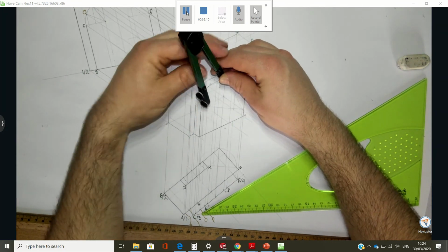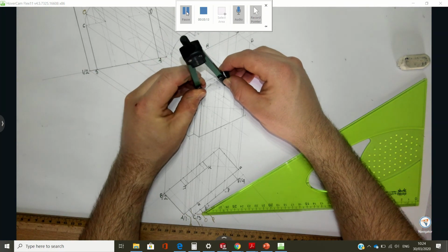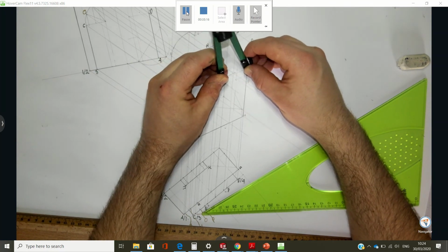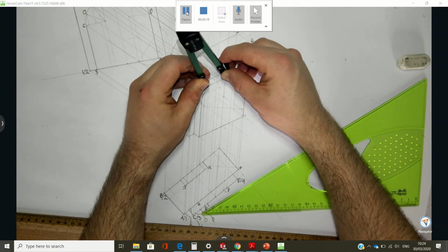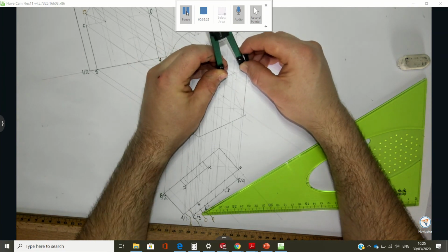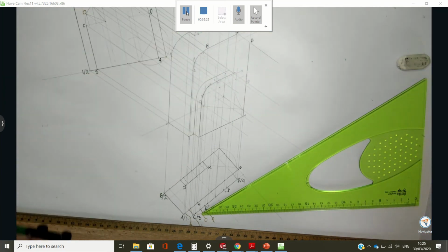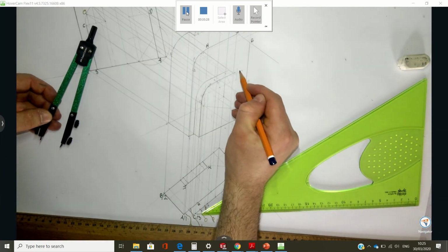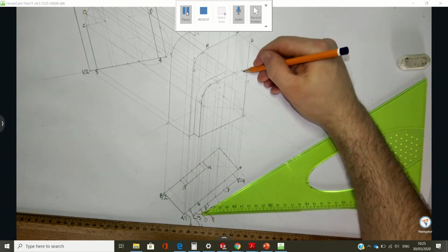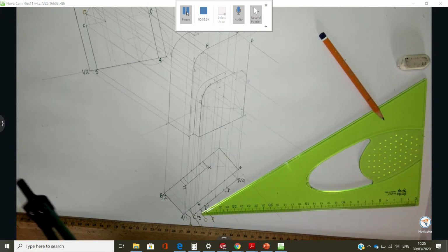Here's the center line. Okay, so O to the center line, step it from here, and then P to the center line, and step it from there. And then I can freehand sketch those points in a minute. I'll do it neatly in a moment there. That's just a reference there to show you where it's going to be.